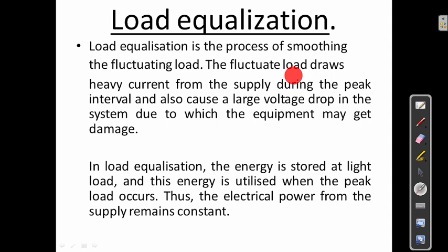The fluctuating load draws heavy current from the supply during the peak interval and also causes a large voltage drop in the system, due to which the equipment may get damaged. If there is no load equalization, then there may be a heavy current from the supply side.